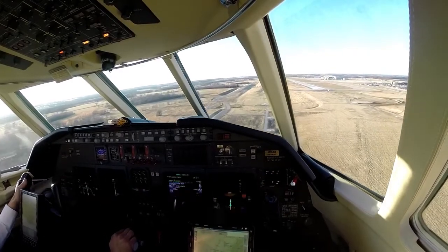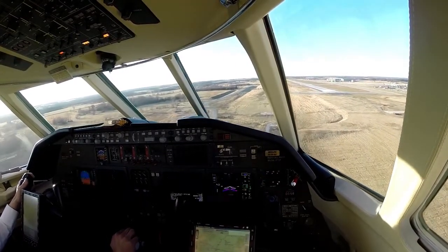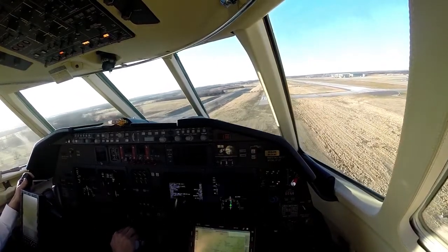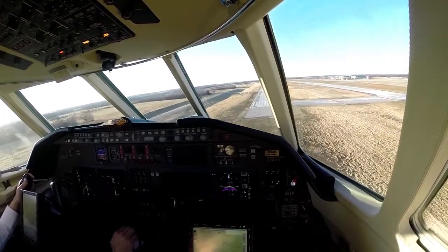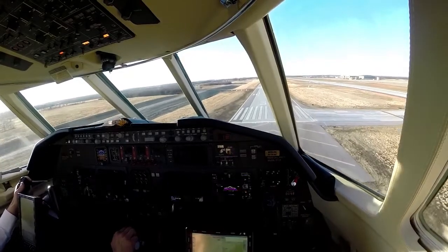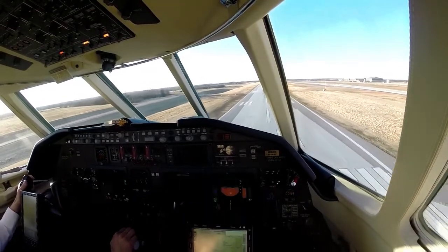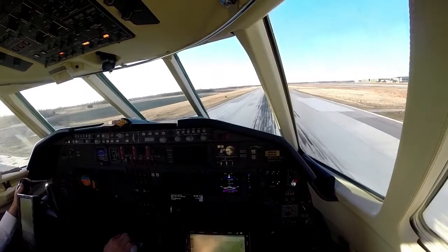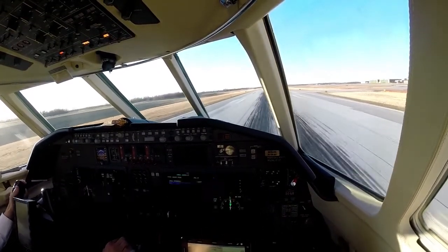Runway safety areas differ by airport. Class 1 airports with air carrier operations, like XNA, have larger RSA requirements and are required to publish a declared distance for every runway, even if these distances are identical to the pavement length. Smaller Class 2 airports, like Springdale, have reduced RSA requirements.